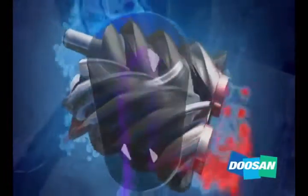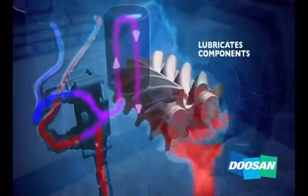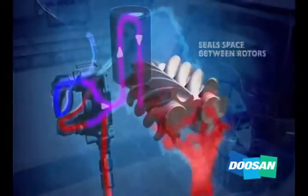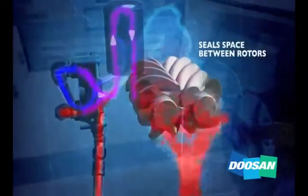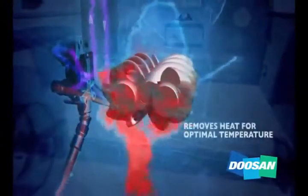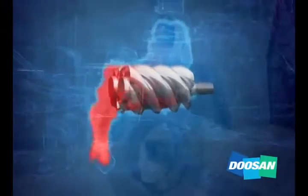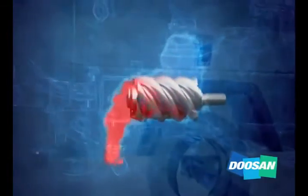During the process, oil is injected into the rotors and serves three critical purposes. 1. To lubricate the rotors, bearings, and seals. 2. Seal the space between rotors to keep pressurized air from escaping back to the inlet. And 3. Remove heat from the system so the air end can run at optimal temperatures. Using oil to maintain proper temperatures maximizes efficiency of the compression cycle.